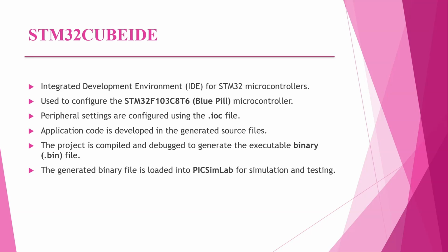Application code is developed in the generated source files. The project is compiled and debugged to generate the executable binary .bin file. The generated binary file is loaded to PicsimLab for simulation and testing. Then we can see the code we run being simulated in PicsimLab by using the .bin file.